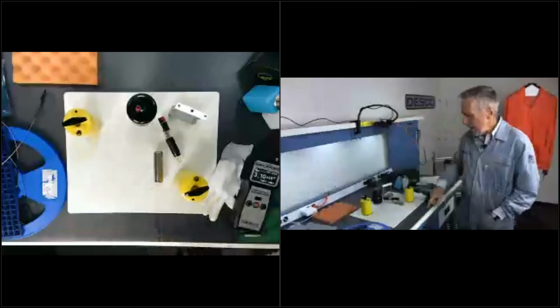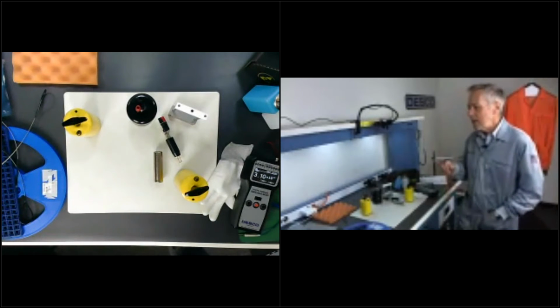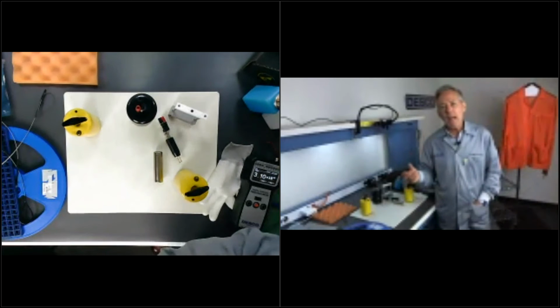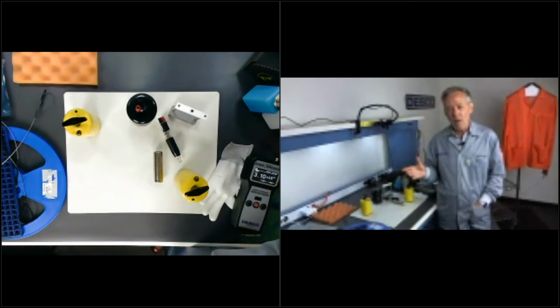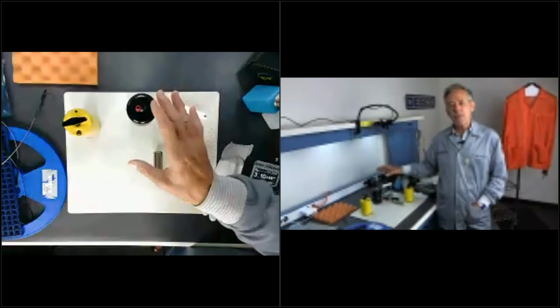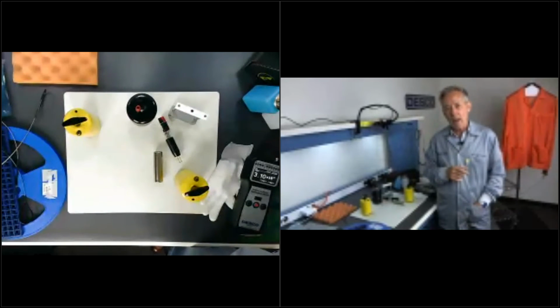I would take my mat and ground it to the steel leg of the bench. When it comes to ground rods, they were typically used back in the original days of static control, when we didn't know as much as we know now. But actually the AC ground is the preferred method to ground.